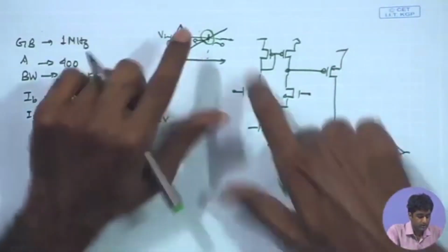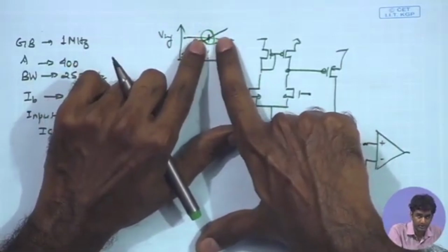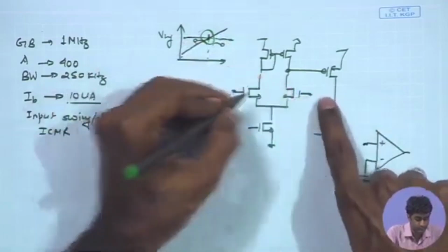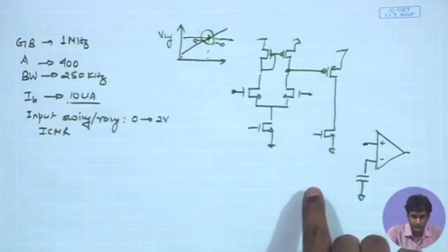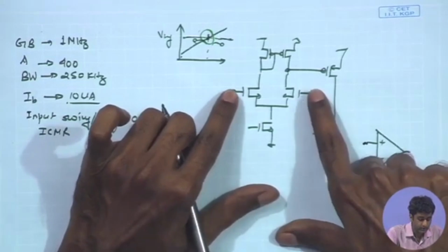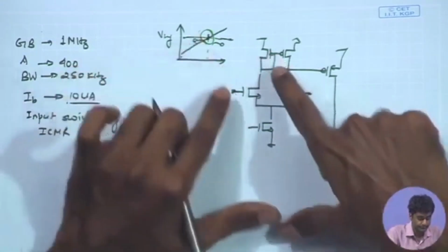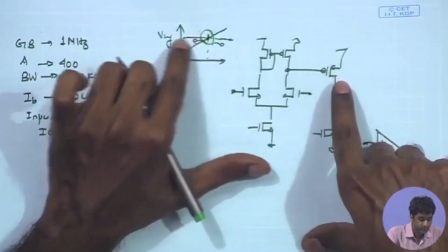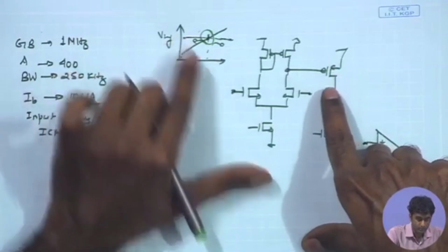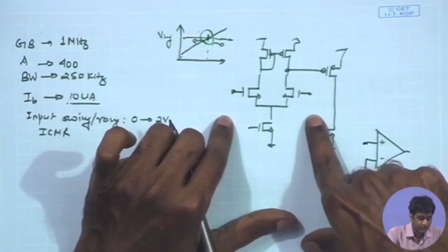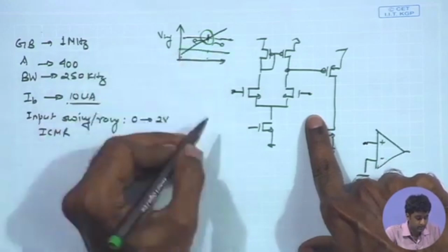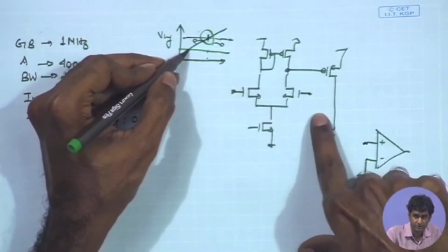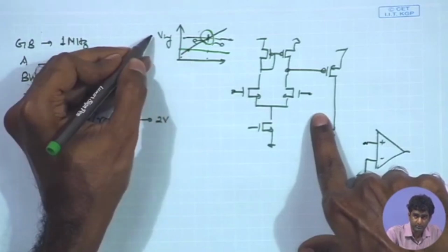So, we are interested in the comparator transient close to this particular point, and therefore, at that point we can see that both these signals are going to be almost close together, right. And at that particular point, I have to make sure that the comparator is going to work fine for the sampled input level, because if the input level sampled is too low, I would expect that the comparator should work fine while the V ref, the ramping voltage, is very small, equal to the sampled input voltage.